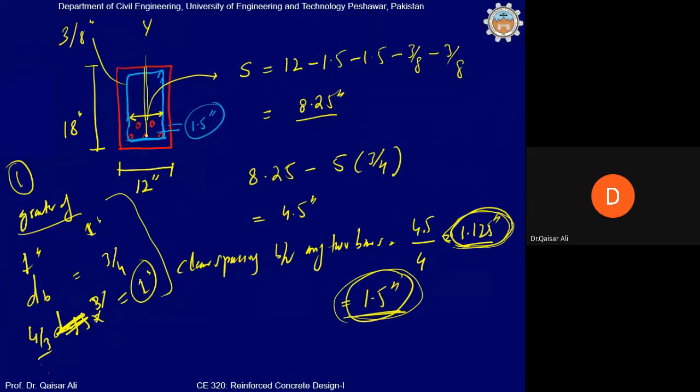If we look at it, the bars provided on the left and right side, they are equal, they are symmetric. But there is another fourth rule of drafting, that this is also not allowed as per the code, because the rule says that each bar in the second layer shall be provided exactly over the bar of the first layer. So इसमें आप देखें, this is not lying over the bars of the first layer.